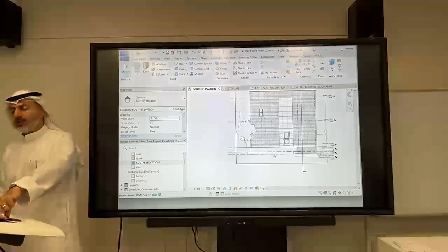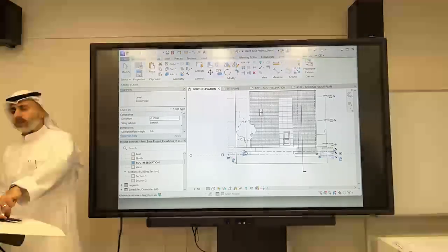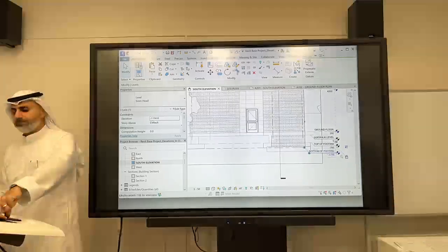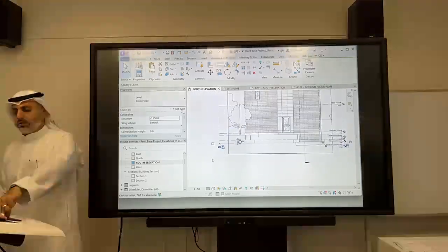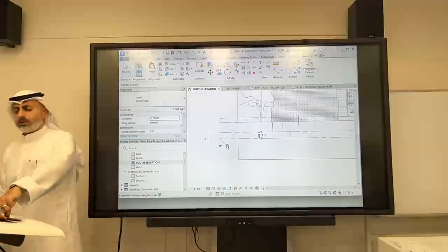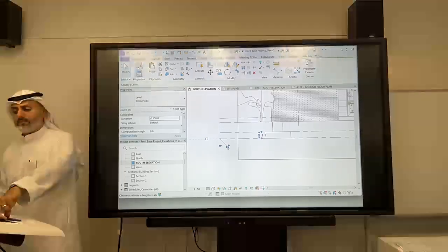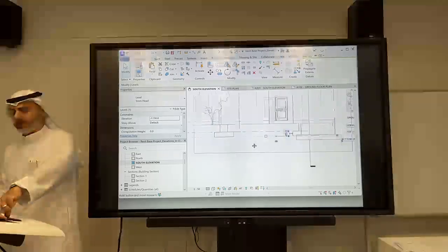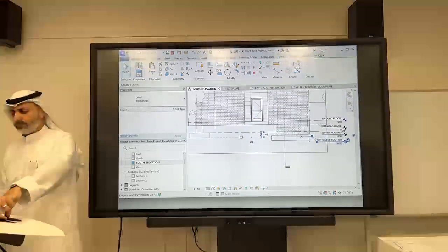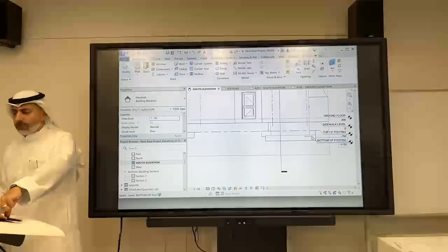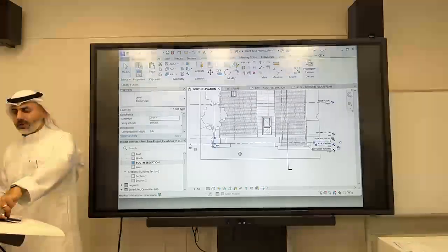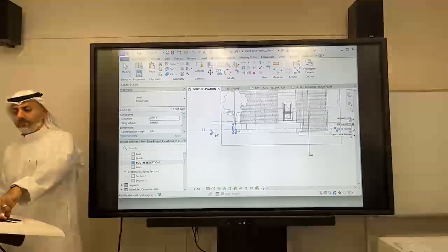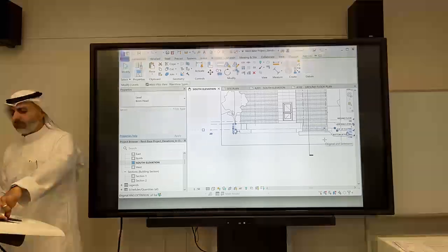The footings, we don't need the lines to go all the way through. So you can click on the levels, let's say the bottom footing. Uncheck the lock technique, and then you can click and drag the line to bring it inside. Do the same thing with the one above. Unlock it. You can click and drag.